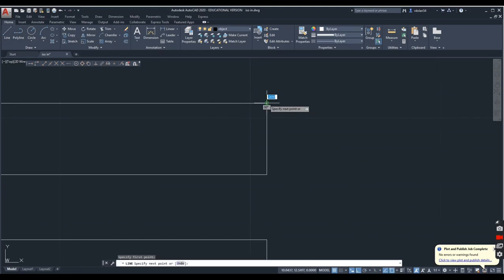To start off, I'm going to draw a construction line from here to here and from here to here. Now I'm going to offset this half of the pitch and I'm going to offset this a pitch. That way the crest of the threads are shifted a little bit. Our pitch is 0.042, so I'm going to go 0.021 from here to here, and then I'm going to offset this bottom one 0.042 from there to there, and I will offset this one from here to here, 0.042.